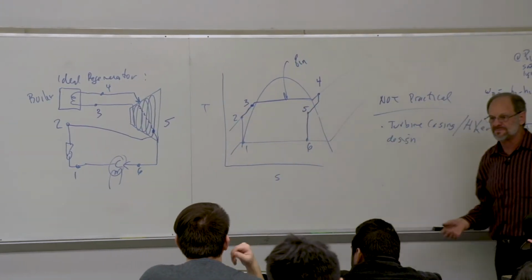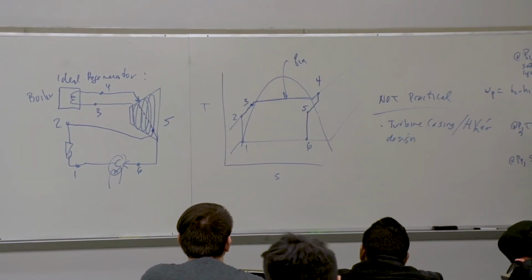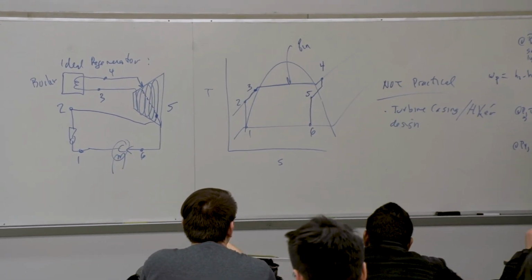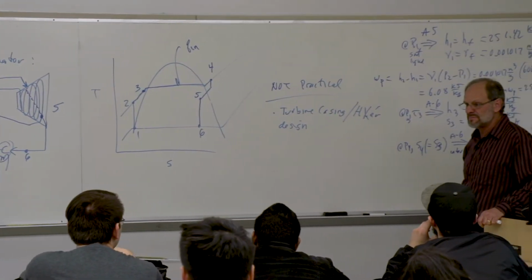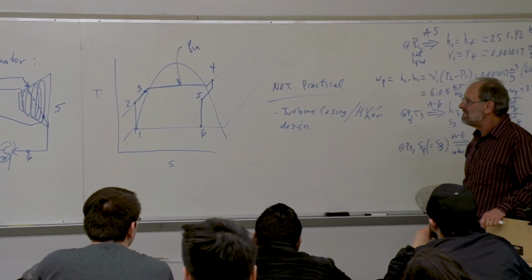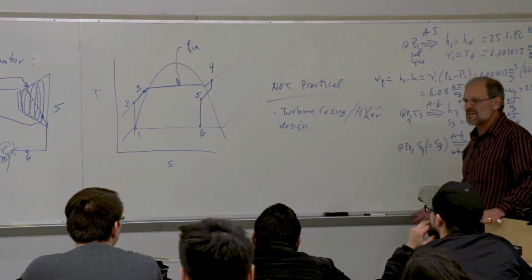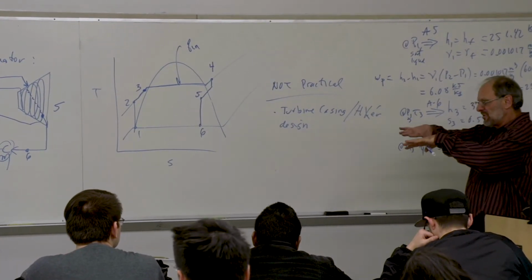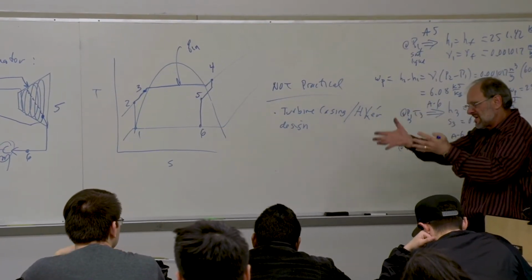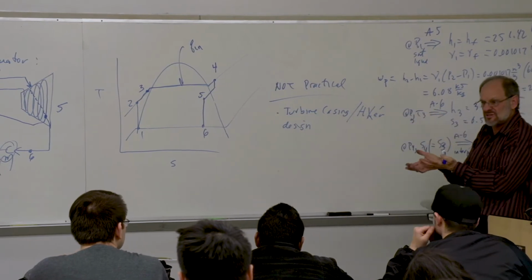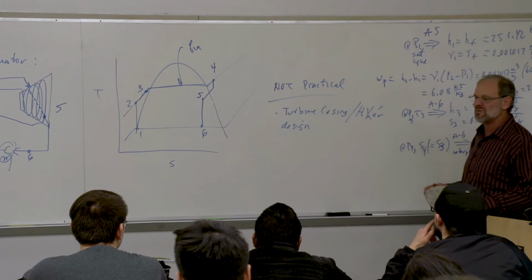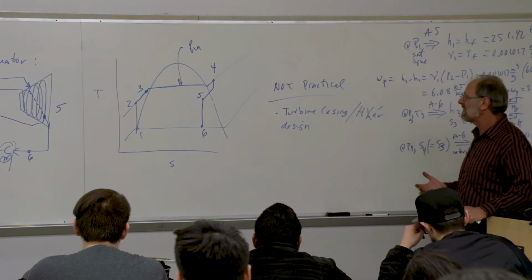Is there a question? I was going to ask, because you want your turbines to be adiabatic, right, for the max possible efficiency, or as insulated as possible, so that coil would have to be inside the turbine? Well, basically, it would have to at least have the ability to transfer heat. So I suppose you could have the moving blades and then have some inner casing with the heat exchange surfaces and then an outer casing. But still, it becomes problematic to do the design.